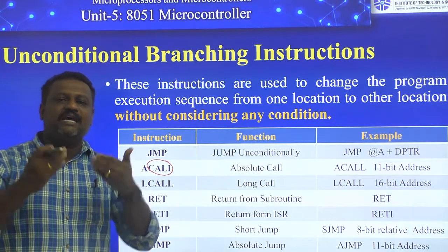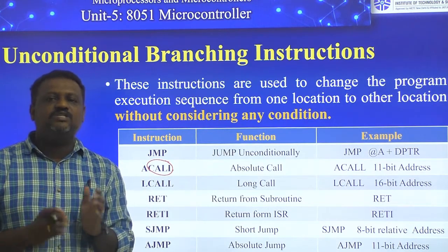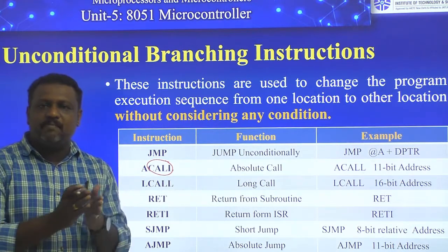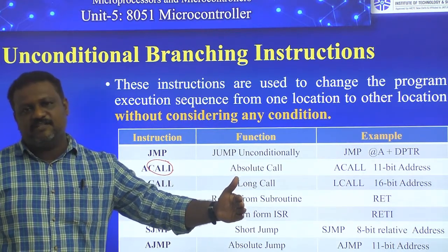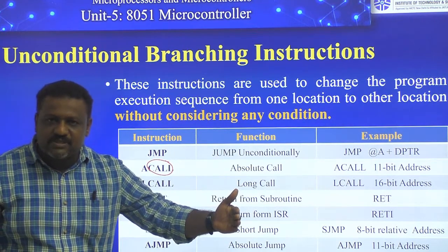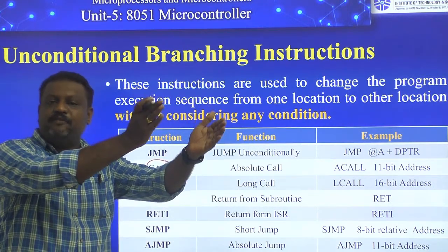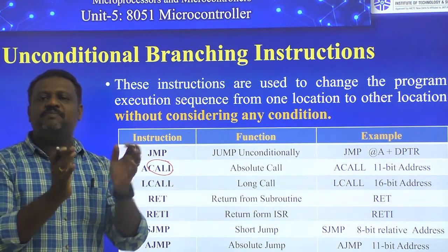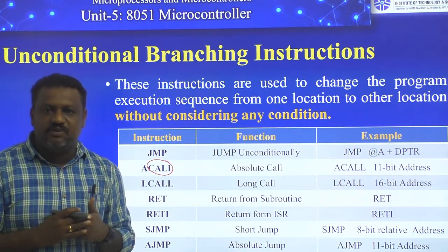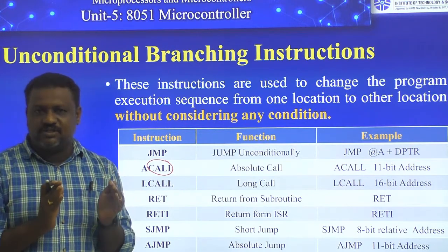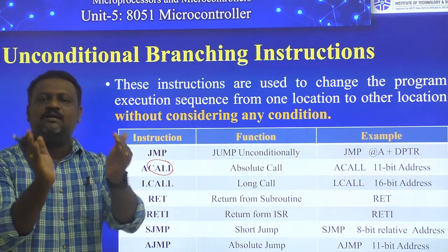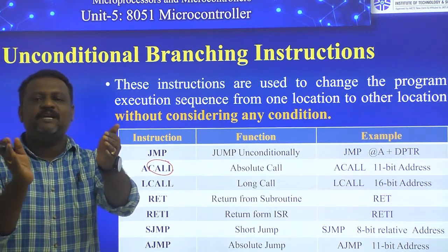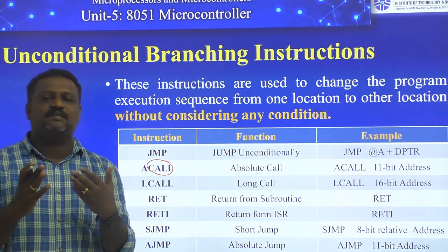Due to this, the advantage I was getting is, instead of writing those instructions n number of times in my main program, the main program size was increasing. Once the main program size increases, it automatically influences the occupied space in the memory. In order to reduce the memory requirement, I can write the instructions needed for a particular operation separately from the main program. That separately written set of instructions I can call a subprogram.